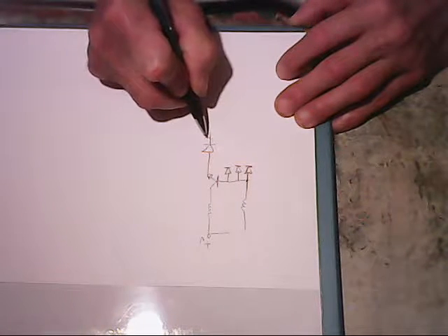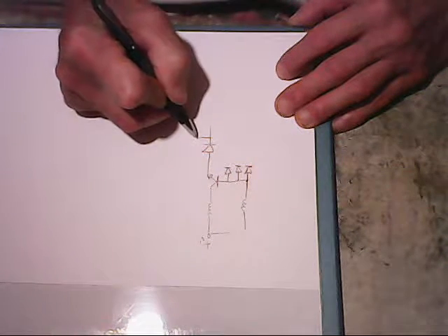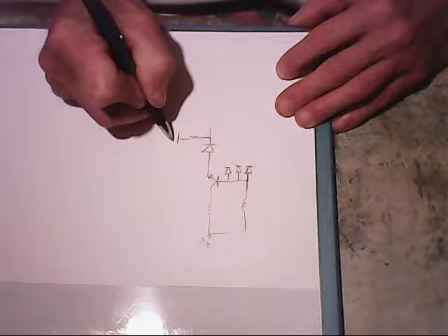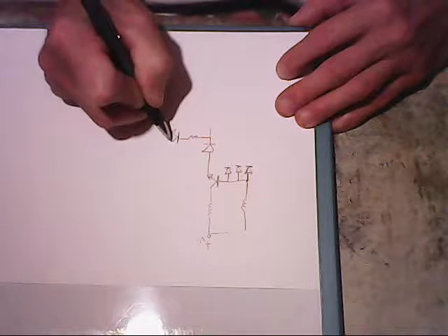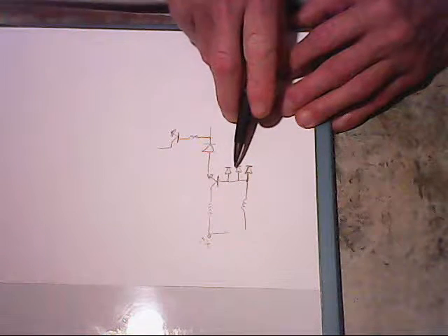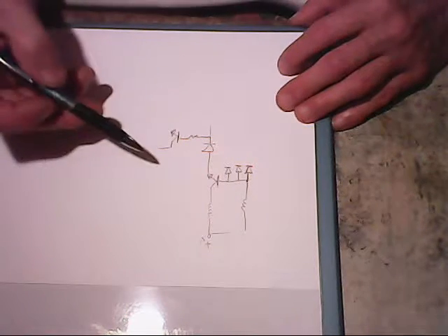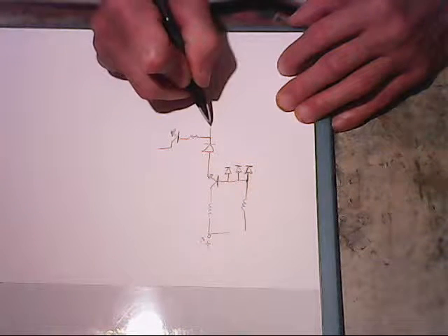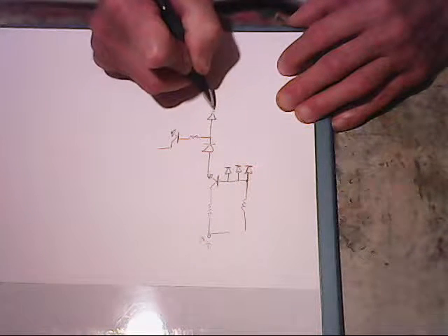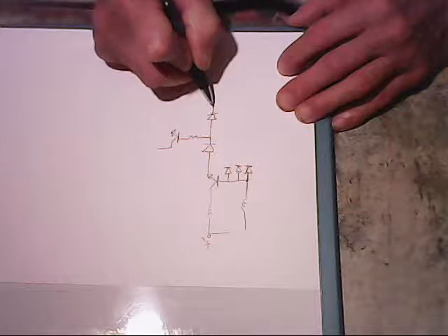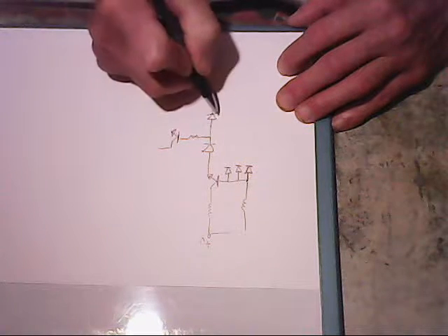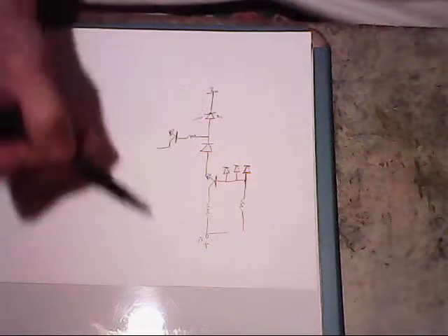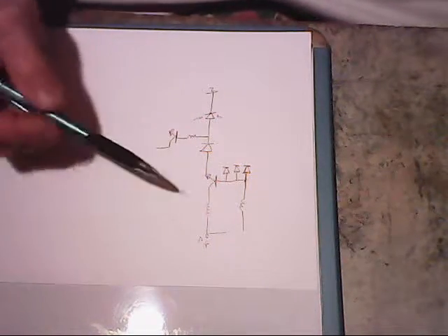Then on the SCR input here on the gate, we will have an input, and then we'll have another NPN transistor that will be used to drive sinking current to the base of the other transistors that will turn those latches off. And of course here would be our LED load to ground. Okay, that should take care of one latching circuit.